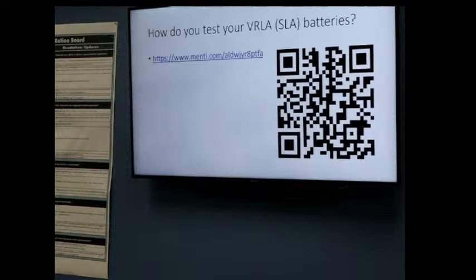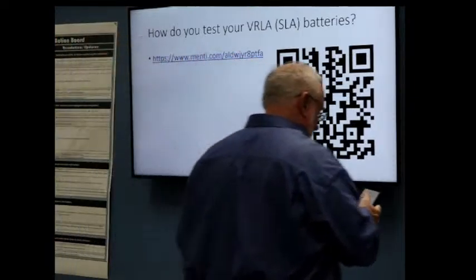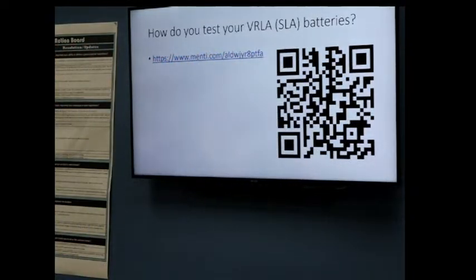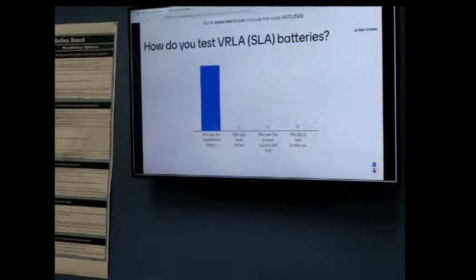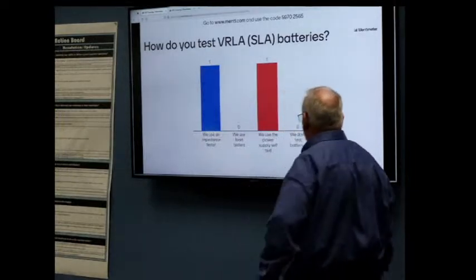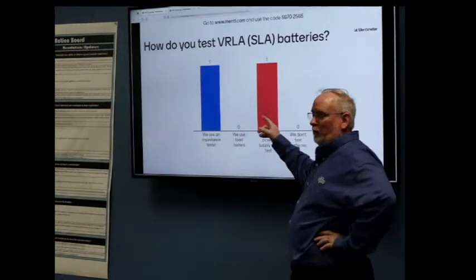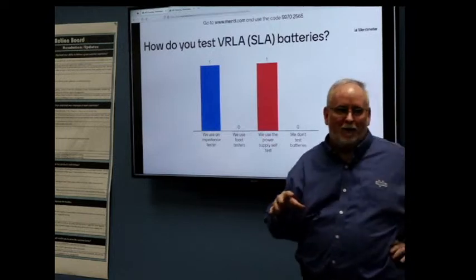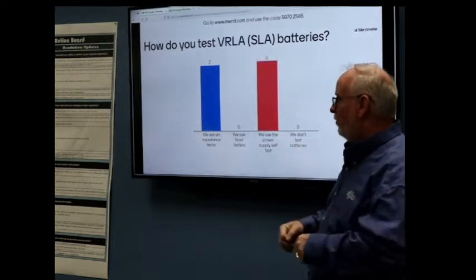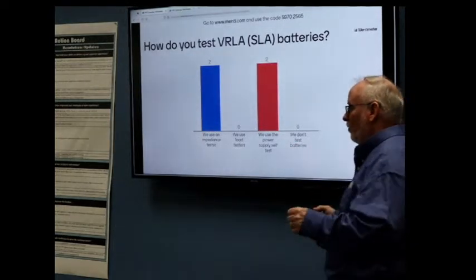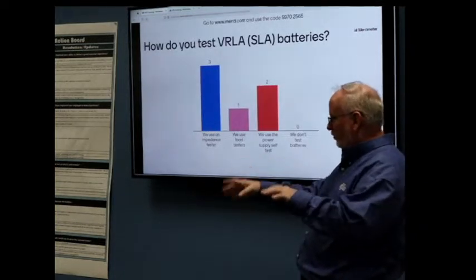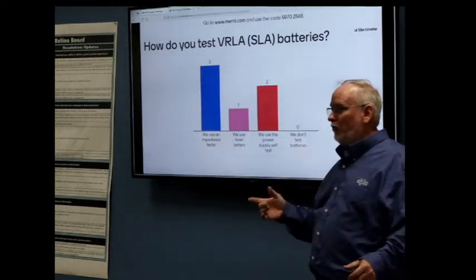How do you test VRLA batteries? Using an impedance meter, that's perfectly legitimate. I appreciate you guys answering this, because impedance meters are not cheap, but it's the only physical way to look at the health of a VRLA battery. There's no other way. You can do a load test and a discharge test and say, yeah, that looks pretty good. But this is your fastest test.